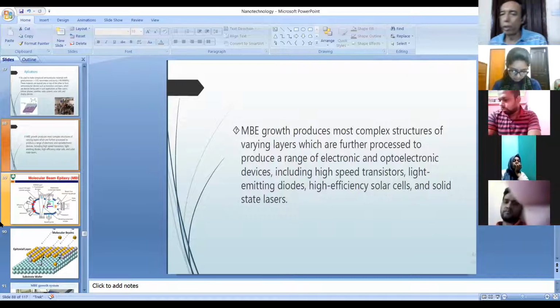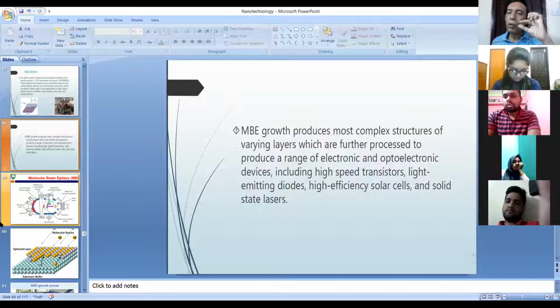So this is known as heteroepitaxy. Homoepitaxy and heteroepitaxy. What is homoepitaxy? You will have a thin film of the same material as the substrate. You have a silicon substrate. Say, for example, you have a gallium nitride substrate, and you have a thin film of gallium nitride. So gallium nitride is crystalline, and the gallium nitride thin film is also crystalline.